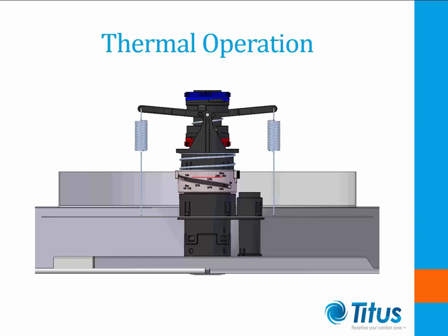A further limitation of thermally actuated mechanisms is that the dead bandwidth, that is, the difference between full on and full off, can be wide. This means that there can be perceptible temperature variations in the space. The advantage of the thermally actuated mechanism is that they require no power and are fairly reliable. They provide limited automatic modulation for small spaces with minimal hardware and cost. They have no external components like a thermostat, so installation is extremely simple.